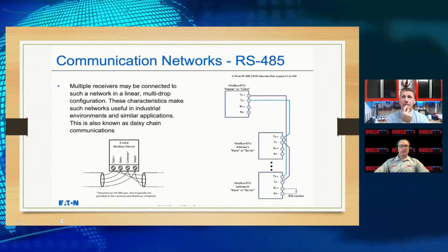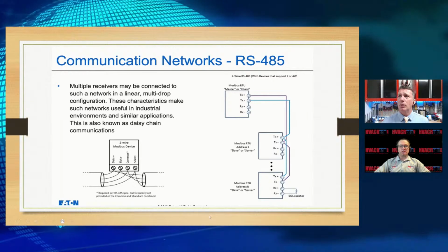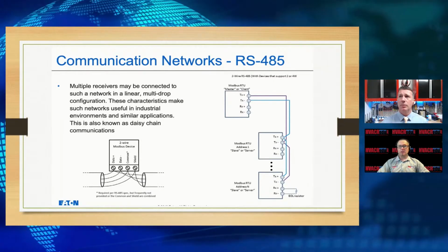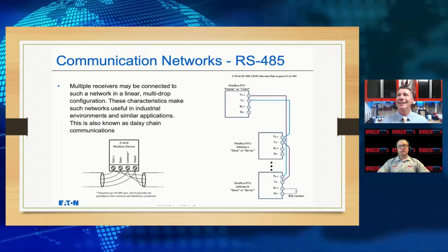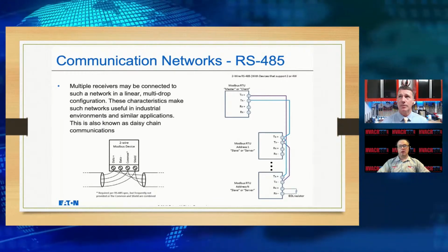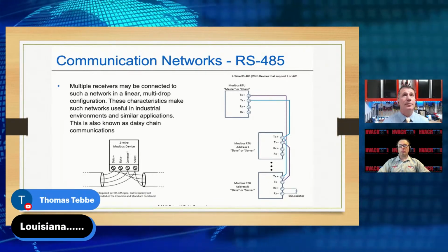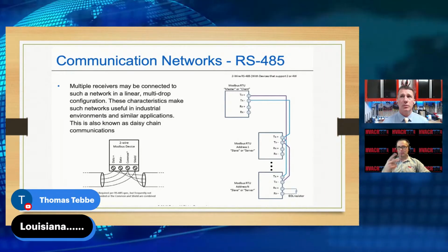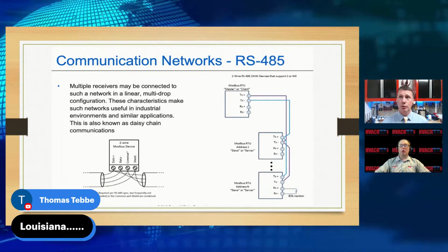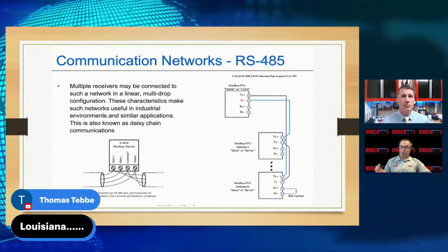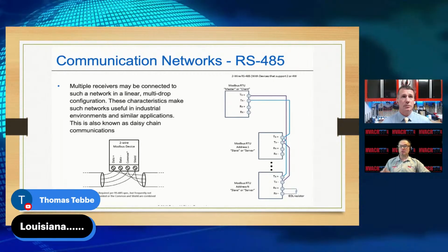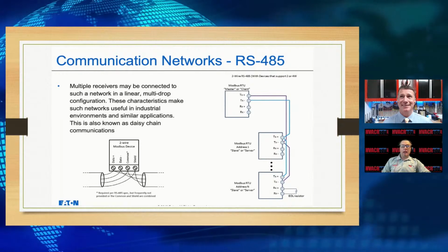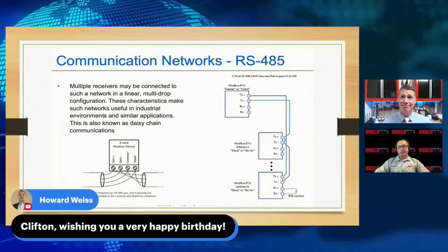Absolutely. And so that communication, here we have a master-slave type application, and this is very similar to the RS-485 cabling that we are used to. Usually a four-wire lead wire, usually two for communication and two, or one for voltage, power to the device. Usually 12 volts, maybe sometimes 24, depending on the device, and then a common, right? You've got to make that complete circuit.